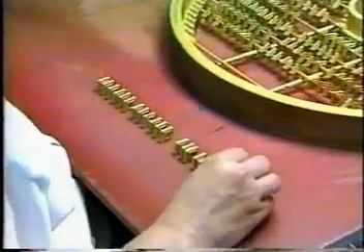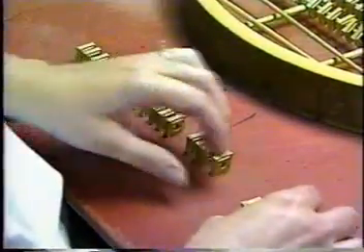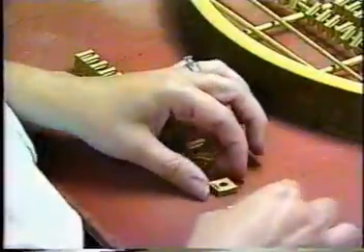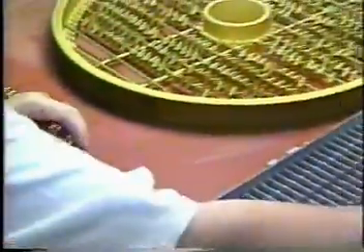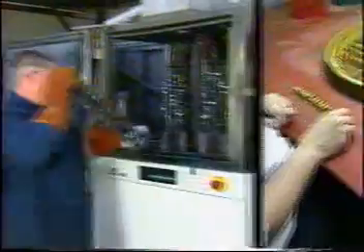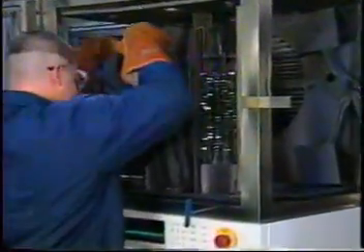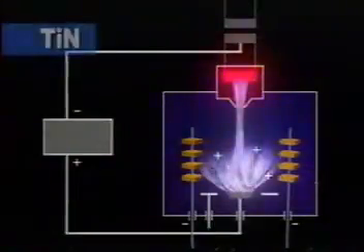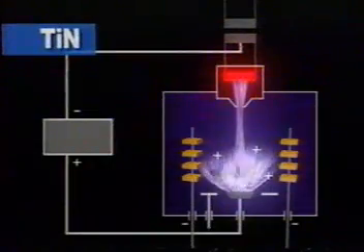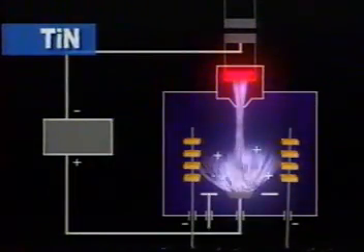Even though they are less than 1/1000th of an inch thick, multi-layer CVD coatings improve wear resistance and provide longer tool lives and higher speed capability. Two processes, ion plating and magnetron sputtering, are in common use for depositing PVD coatings. In ion plating, the metal component of the coating is evaporated from a metal target by a low-voltage arc, while in sputtering, the metal atoms are removed from metal targets by bombardment with argon ions.